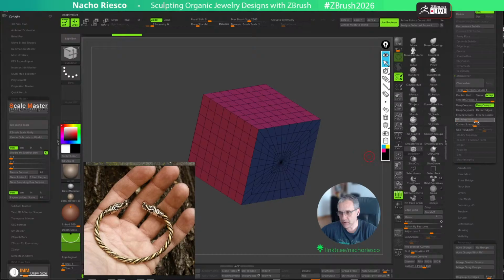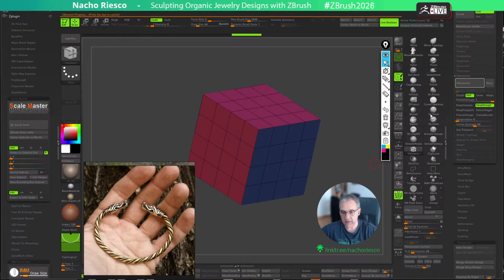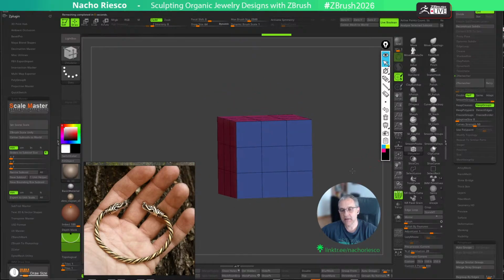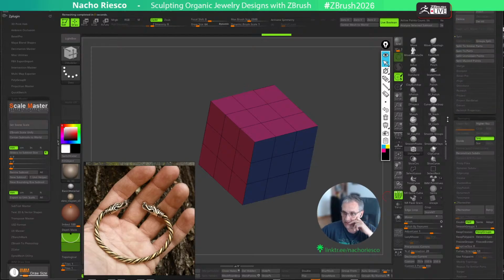That means you should go from 50 to 0, and maybe you are looking for the same amount of polygons, and click on ZRemesher, you will get this. And if you want to reduce the topology, you can change from same to half, and then half, half, and half, till you are getting the right topology to work with. So from this point you can use a completely different topology.